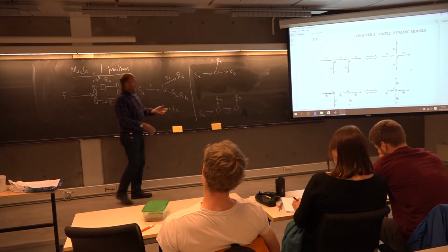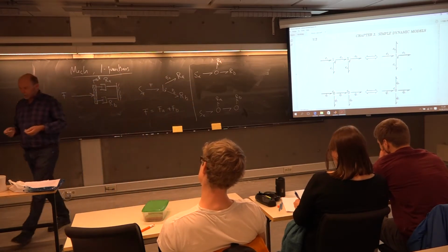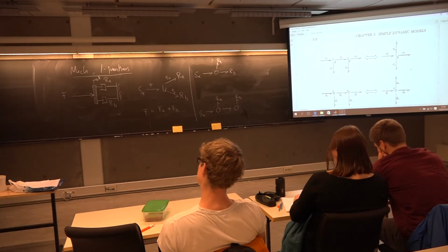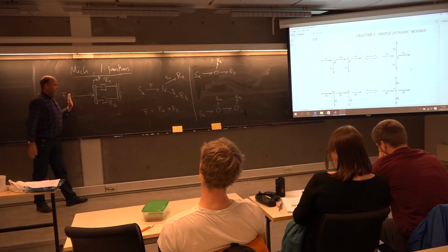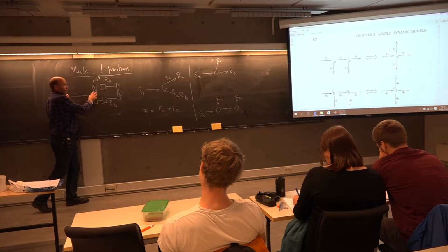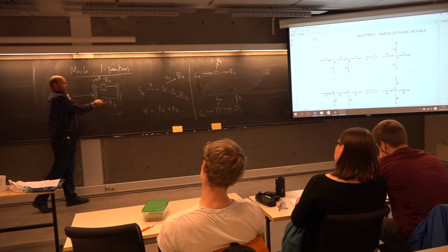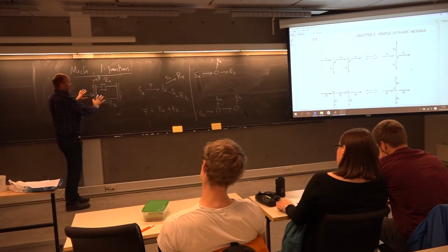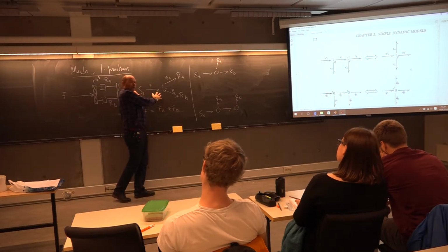Yes, so it's possible to do simplifications. We will have a lot of these rules on how to simplify a bond graph, but already now you should have the idea of what's going to happen. You have your physical layout of your problem. This is where you start. Then, using bond graphs, you will identify different elements: zero junctions, one junctions, resistance, inertance, springs, and then you will remove the physical image and just be left with a graphical representation of the real problem.